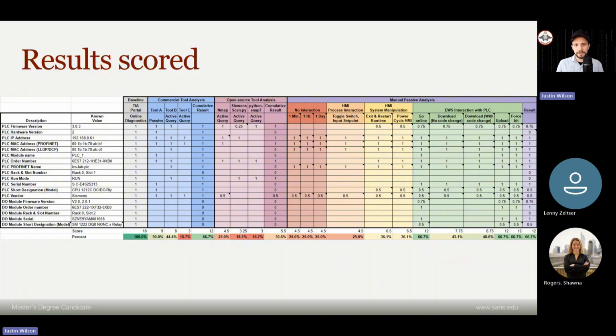And then I tried going online or connecting to the PLC and downloading new code, performing a download with no new code, uploading existing code, etc. And what I found is that simply going online with the PLC, just connecting to it and not doing anything beyond that point, produced a great deal of asset information to be transmitted and captured.